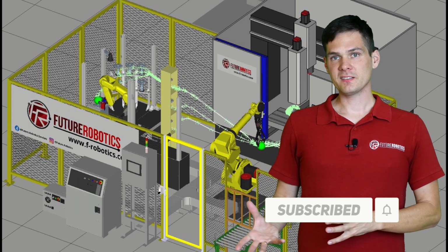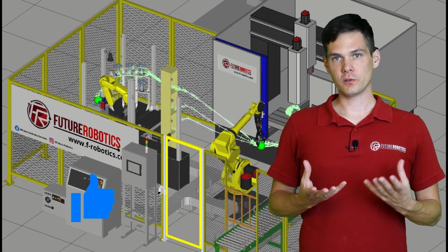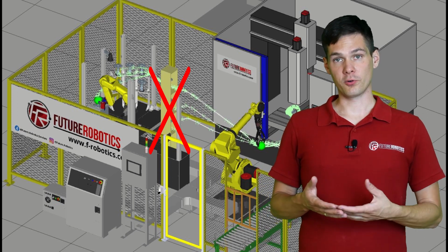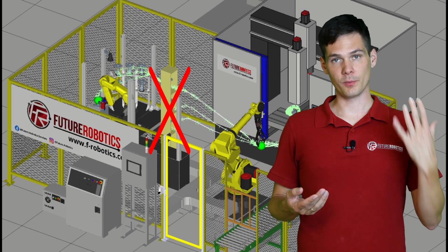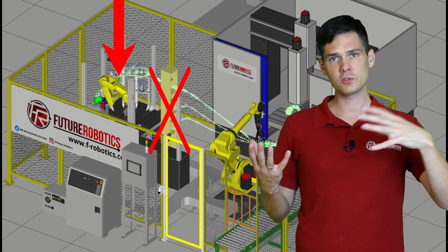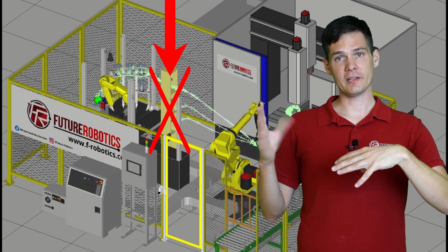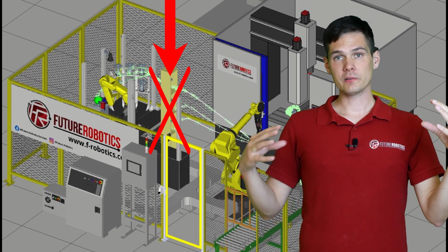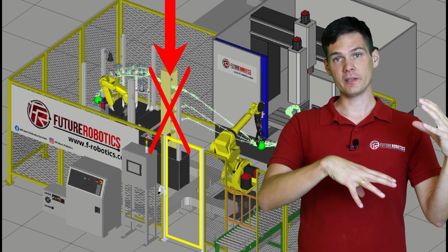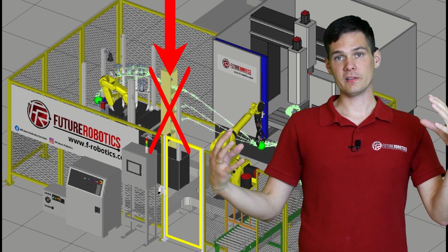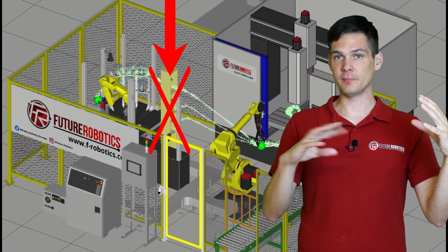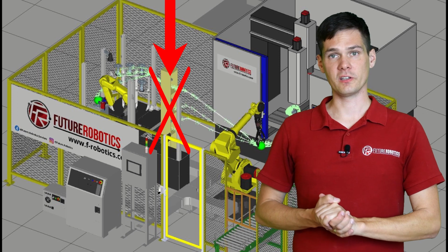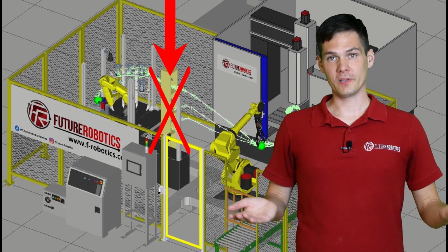Just like I said very simply, we will use the collision zones to tell the other robot not to enter some area of work because the other robot is performing work there right now. So if we have robot 2 and robot 1, if robot 2 is right now in that zone, it'll tell robot 1, hey, don't go inside because I'm working there, please wait for me to finish. Then robot 2 will go out, robot 1 will go in, and once it is able to go in, it'll say, now it's my turn, do my work. After it's done, it'll go out and the process is going to be completed.